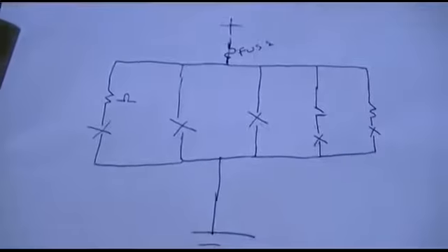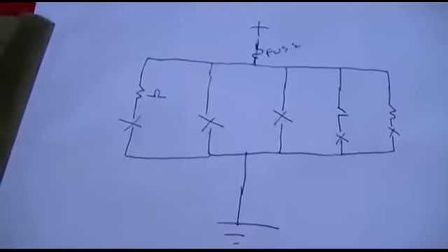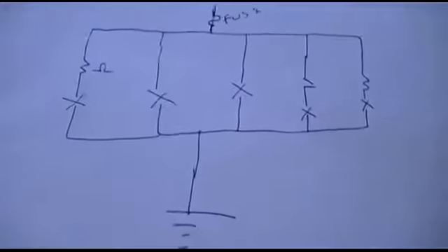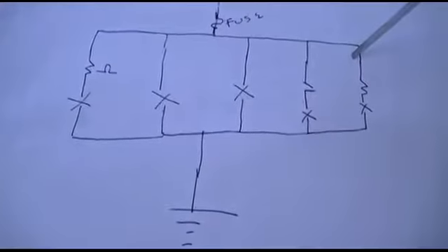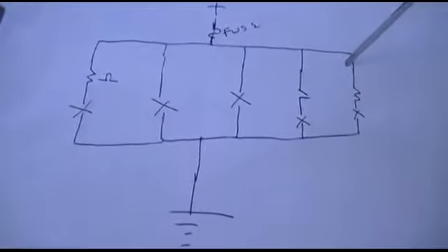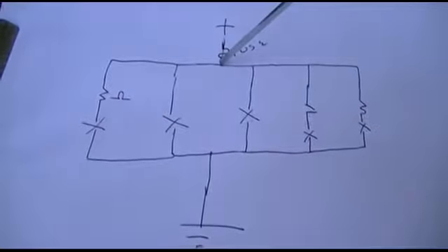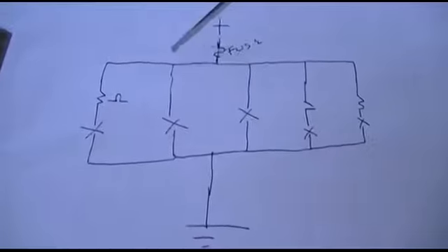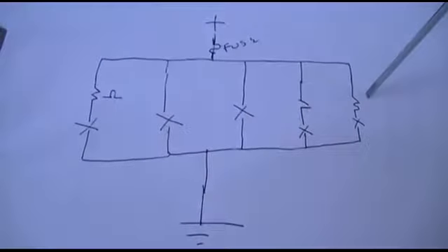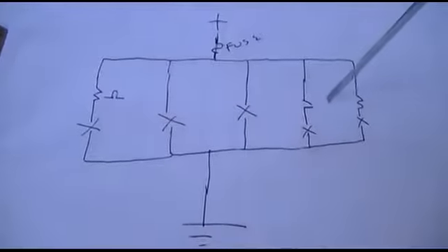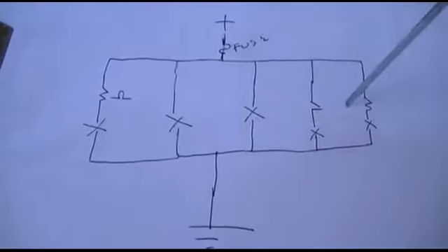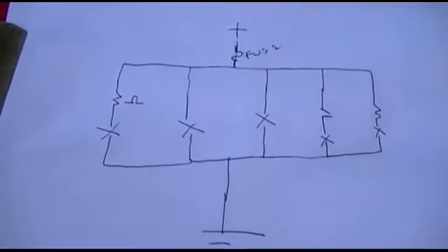Okay, now there's a much cruder kind of third world method that I didn't mention. Of course, the proper way is to go through and disconnect these one at a time till you find the load. The cruder way is to bypass the fuse and quickly apply power and see which one gets warm, or just bypass the fuse and see which one explodes into flames.